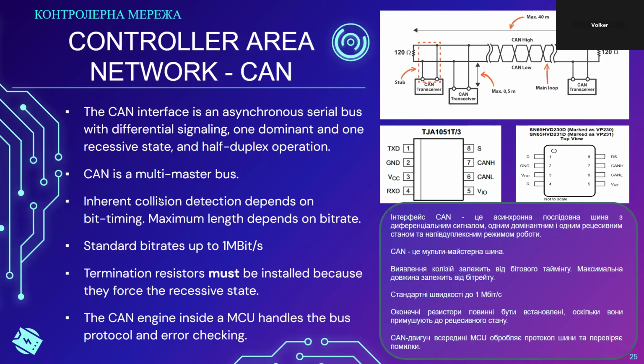Most CAN transceivers have the same pinout. You can see that here between those two examples. One is an NXP device, the other one is a TI device. Both use the same pinout. It's pretty much a standard pinout. This is similar to RS-485 drivers. You can have 10 different manufacturers of RS-485 transceivers, and they will all have the same pinout.